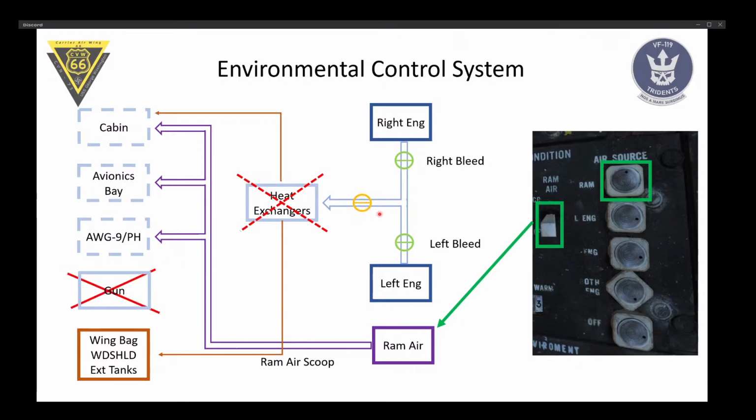The reason why I would want to do that is there's basically two heat exchangers in the aircraft, and if one of them fails, or basically there's a problem with the heat exchange, but you know that the engines and the engine ducts are good, you can go into the RAM mode, and you retain basically more capability than if you were in the off mode.